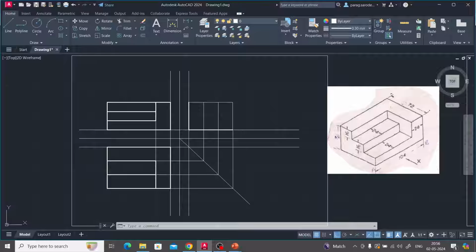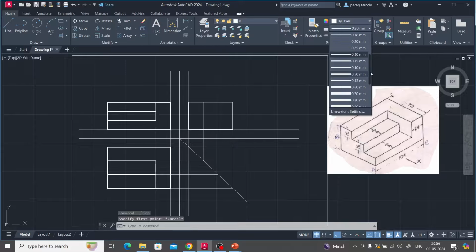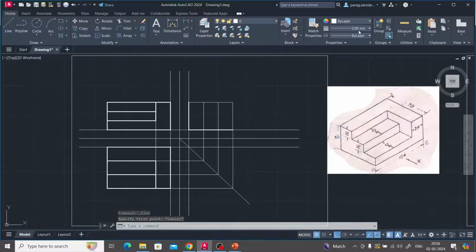What is the height? We are going to get 16. In this case, either we take the 16 or we can just project it from the front view. So how do we project? We set the line thickness again to 0.09, and in this way we get it like this. We take these critical points from the front view.